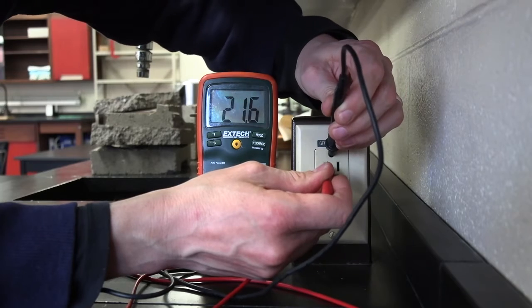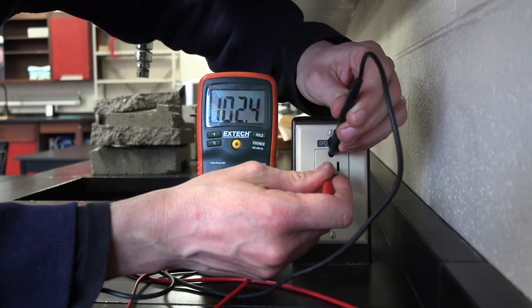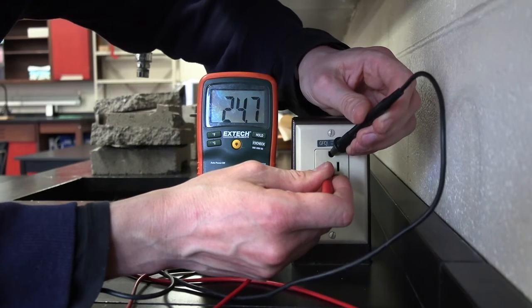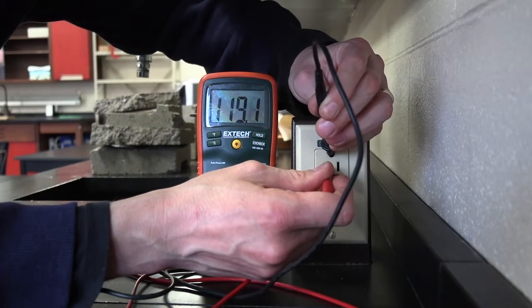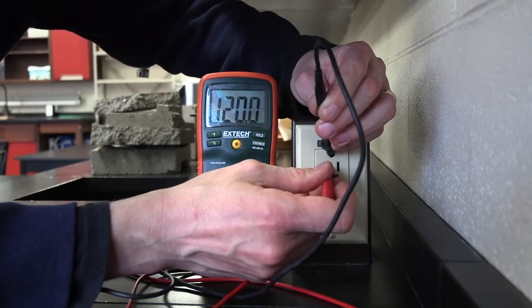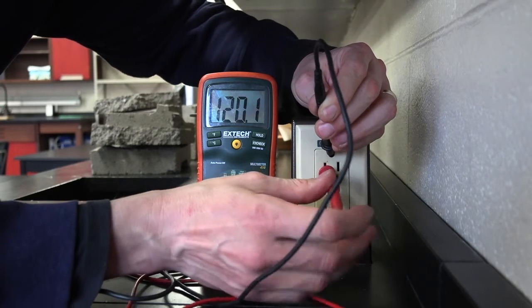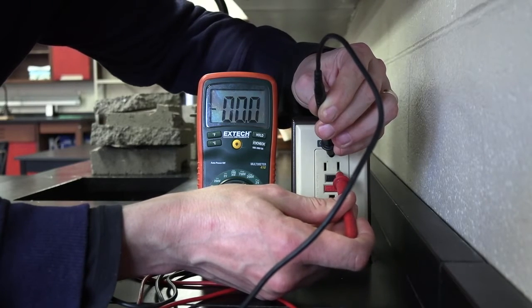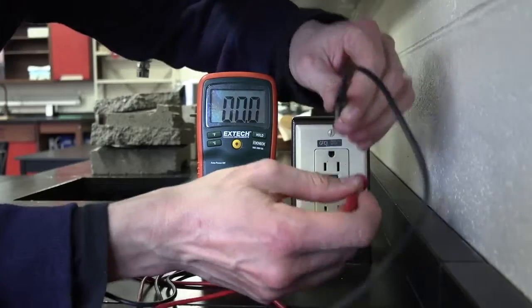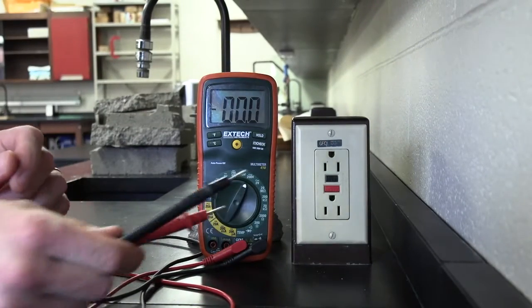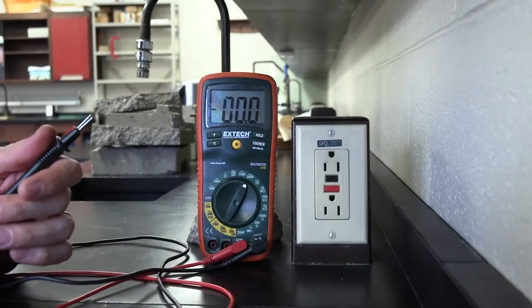I've got to find the right connection in there because the prong size is not correct, but where is it? There it is. So 120 between the ground and the hot. Now, the voltage between the neutral and the ground is 0 because they're both connected to the earth, so there's no voltage difference. So interesting how you can use a voltmeter to even measure the voltage of an outlet at home.